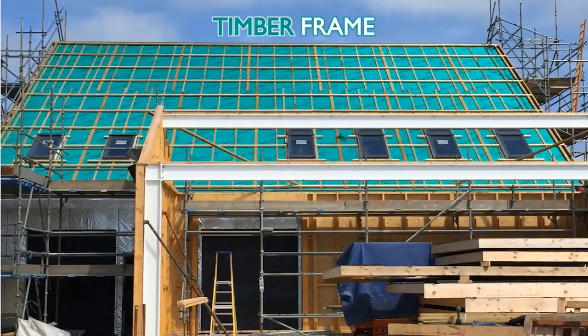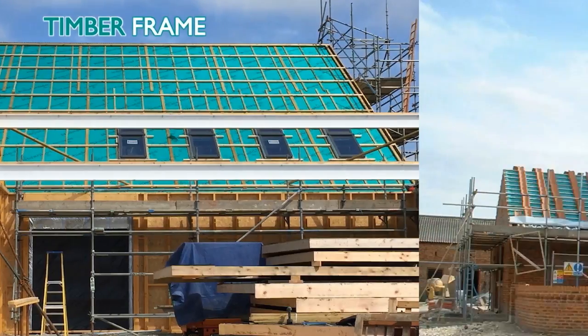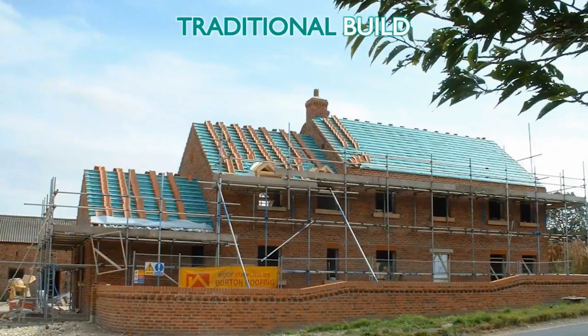Timber frame buildings are typically built under drier off-site conditions, which not only reduces initial moisture loads, but means a wind and watertight envelope can be achieved in less time. Tighter tolerances and better quality control also help reduce problems, but this might mean that the building is less able to tolerate issues arising from poor installation or damage to prefabricated elements that might occur. Traditional masonry buildings will have higher moisture loading from wet trades and less precise construction process that places greater emphasis on good workmanship on site.